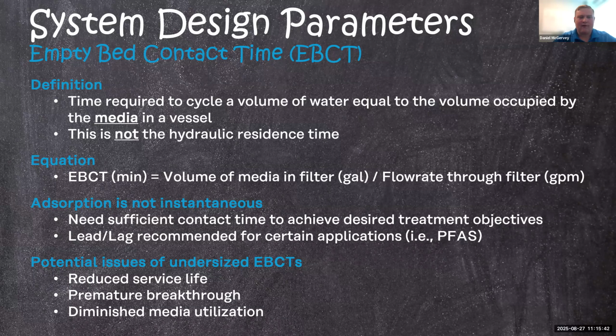And for PFAS, that's typically around 10 minutes is what we would recommend. Some other contaminants have a little bit more of a range, but around 10 minutes per vessel is typical for a contact time for PFAS. Again, because they're down to those extremely low levels, that just makes sure there's really enough time for these contaminants to absorb.